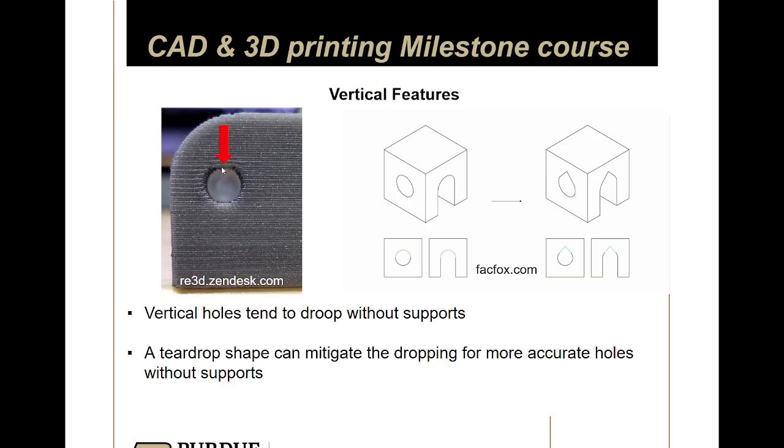So one way to combat this is by removing that overhang by adding a teardrop. If you ever download some 3D printed parts that someone meticulously designed to be 3D printed, you might notice that they do a lot of these teardrop shaped things on holes. That's because a 45-degree overhang is perfectly fine. So if you extend that overhang at the top of the circle and create that teardrop, you create no significant overhangs, and you're typically fine.